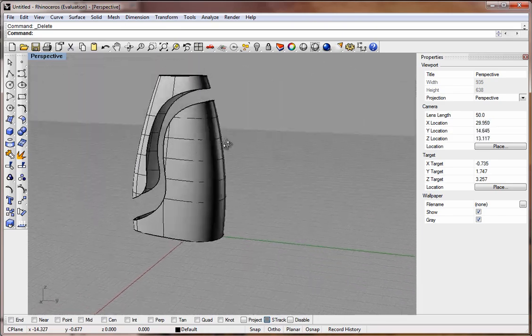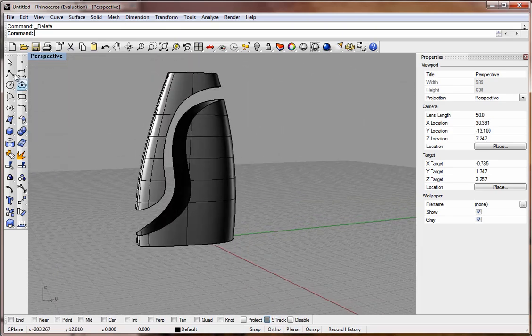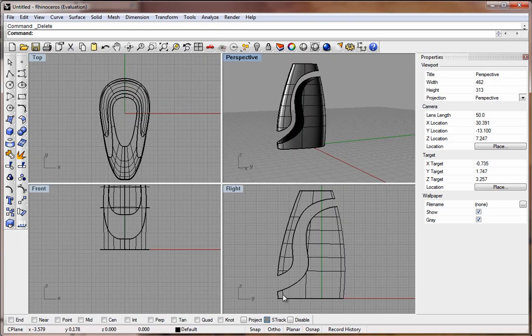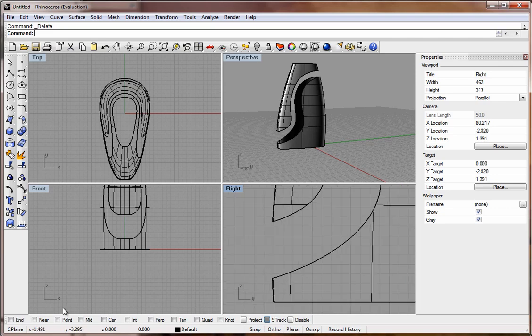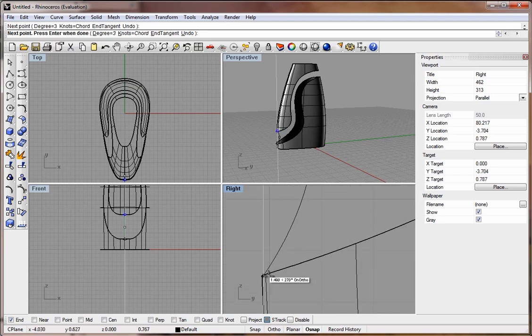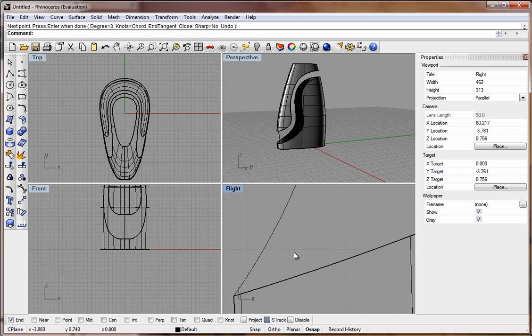Okay, now that we have this, we want to go ahead and draw some geometry in here. So best off going to the right view orientation and zooming up here. And go to end and select the same curve tool. Find the end right here, click, drag this out a little bit, make a little scallop inside there, and find the end over here. There we go. Then right click to end that curve.